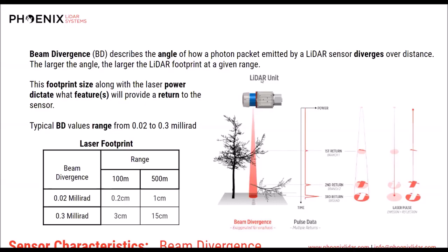Even though you might not get quite as tight of vegetation penetration for a given beam, the fact that you have 32 of them increases your odds considerably of penetrating vegetation versus just one laser. And also simultaneously, if you get that one laser that hits the ground, you have 31 lasers that will give you a better understanding of the features above it.